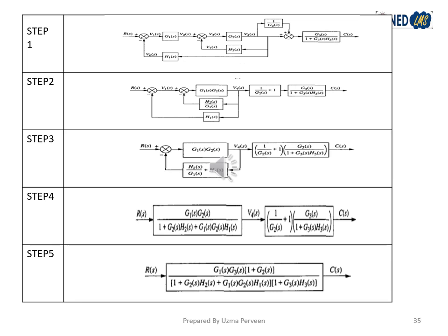Then in step 2, we have combined the parallel path 1 upon G2 plus 1, and then the next step is very clear because we have combined cascaded blocks in the rightmost side, and we have added the summers as we have done in the last problem.